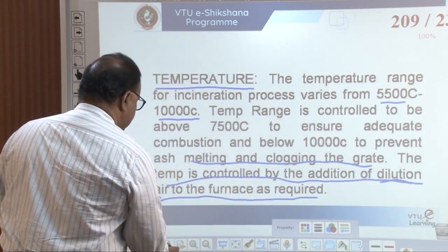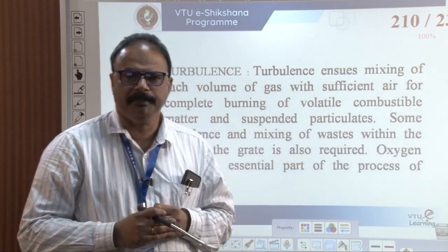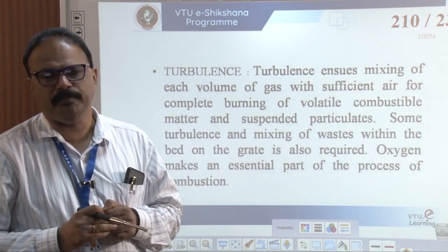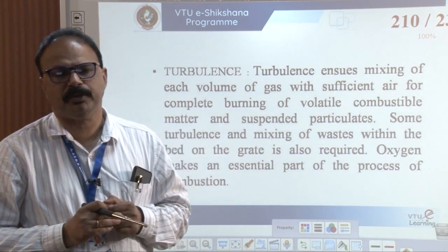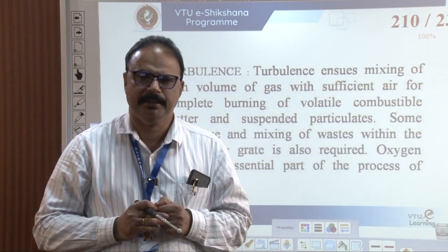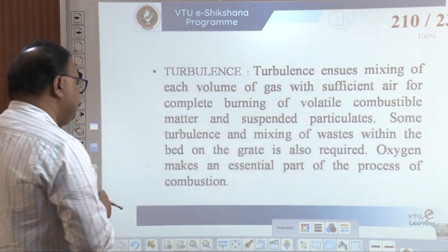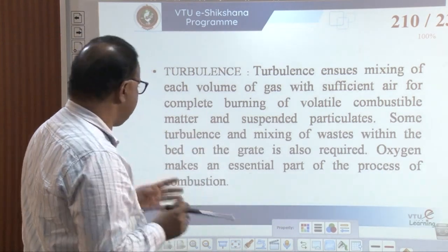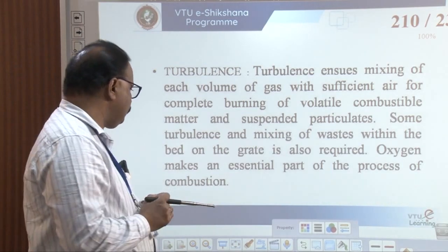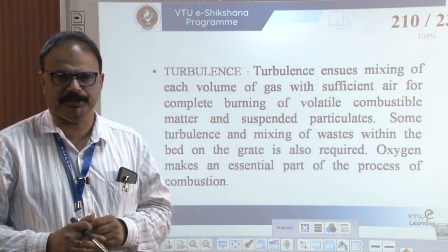Okay. Then third one, turbulence. Turbulence ensures mixing of each volume of gas with sufficient air for complete burning of volatile combustible matter and suspended particulates. Some turbulence, or mixing of the waste within the bed of the grate, is required. Oxygen makes the essential part of the process of combustion.